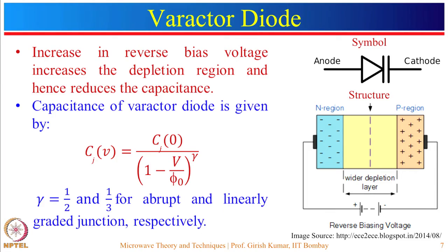Similarly, in case of a tunable band pass filter, if the Q factor is high, the tunable filter will be more selective, or the response will be steeper. So depending upon the application, Q factor should be chosen. Now we know the Q is inversely proportional to the C value and the series resistance. So there is a trade-off between the capacitor value and the quality factor. So one should choose the capacitor according to the application.